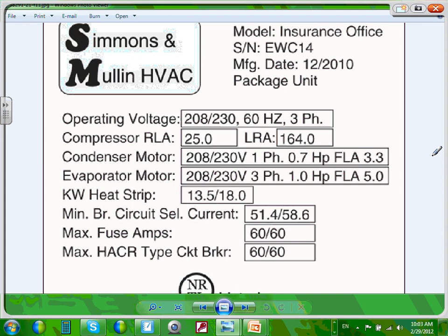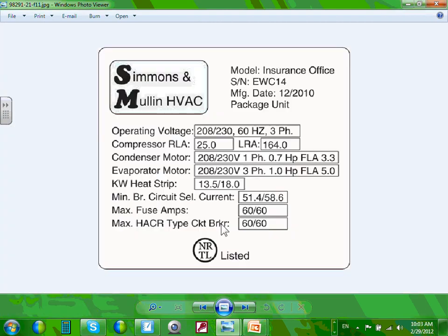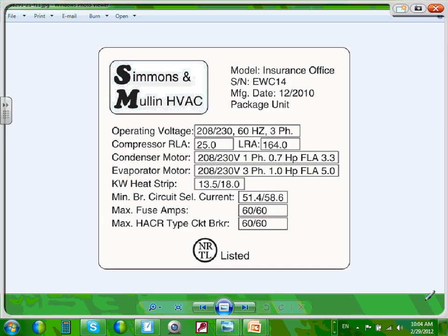Maybe I can look at rooftop units and chillers and all this good stuff, especially equipment. Systems like this have a nameplate. HVAC equipment has a nameplate. Everything is in the NEC code book, NEC Article 440. If you go there, it will tell you that because this is a special system, the cooling system, we want you to use what the manufacturers give you right on the nameplate.